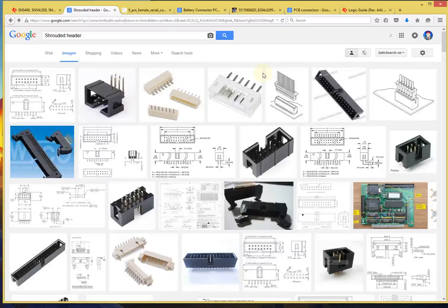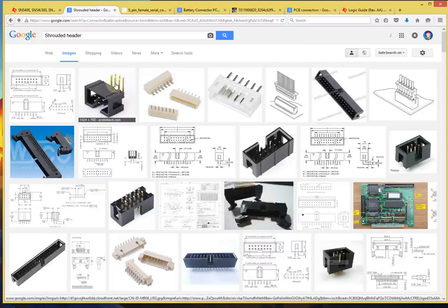You know, what parts you use depends on a variety of criteria, such as environmental conditions, temperature conditions. Is the part going to go into an oven where you do soldering reflow for your parts, and it needs to withstand high temperatures? Is the part going to operate, or the board going to be in high temperature conditions, low temperature conditions? What are the electrical characteristics and constraints of the part? How much current, how much power does the part have to be able to withstand? All of these decisions come into play in you deciding.